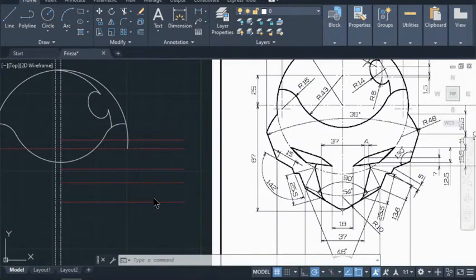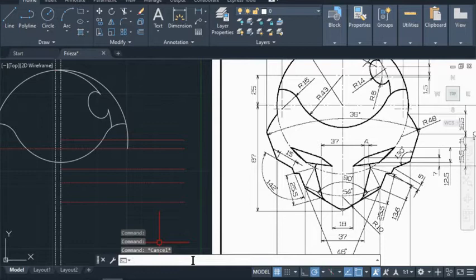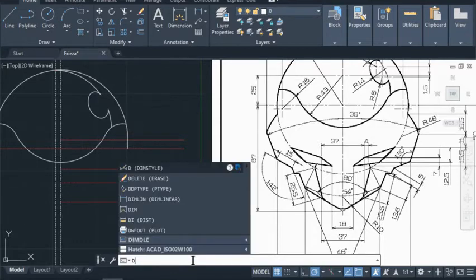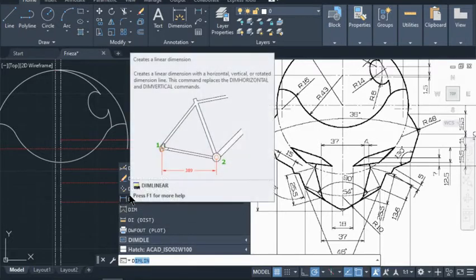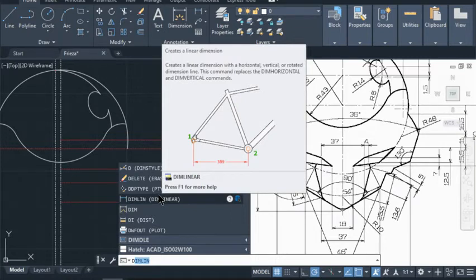All right, so let's see what we're gonna do next with this. Here we are at this location, and for the next steps, we're gonna go ahead and do this arc, and everything's on the right hand side here, and then we're gonna mirror it to the left. But first, because we have different kinds of construction line here, they're all the same colors, and we don't know the difference. If we go back and forth, we can see the measurement there. But another thing you can do is put in the dimension yourself. If you tap D on your keyboard for dimensions, you can see the linear dimension. That's the one we want. You can see the dimension that's linear. You see that they show up the picture between two things, right?